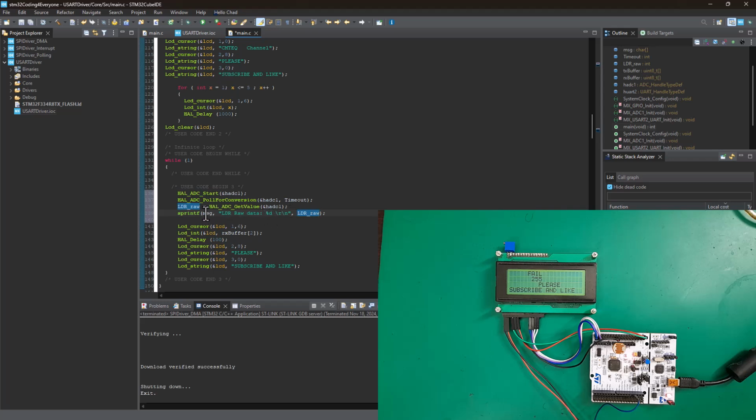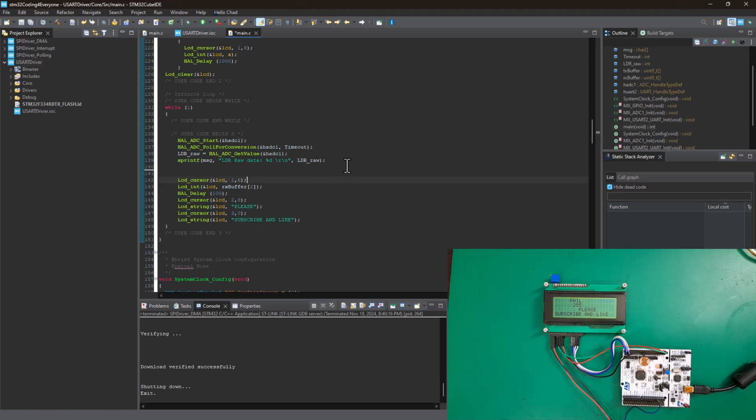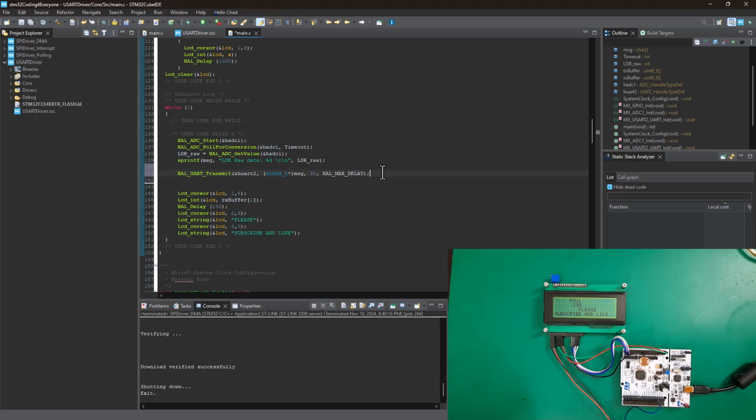We're taking all of that and passing it into this character array msg. Great. Now the next thing we need to do is call the transmission function that will take this message that we just coded with the string and the raw data, and pass it to the transmission function to take it to the next step, basically to pass it to the virtual terminal.